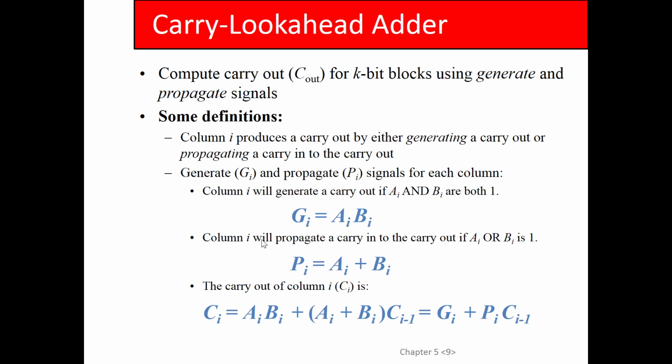Every time the signal has to percolate through a full adder, it has to go through several gate delays, right? Does that make sense? If you implement your adders in sum of products form, or product of sums form, every full adder is 2 gate delays. So the number of gate delays will be 2 times the number of full adders you have to propagate through.